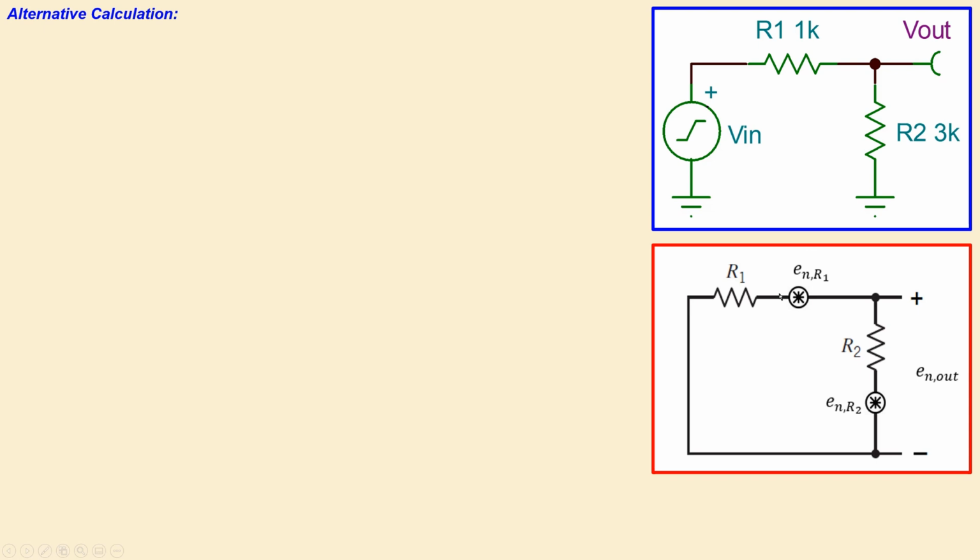I already said that in the beginning. You can also place the R1 in parallel with our noise current source, noise current spectral density. That's also possible. It can be also done for R2. It's actually what you prefer, but I will now do that by using the Norton equivalent circuit.